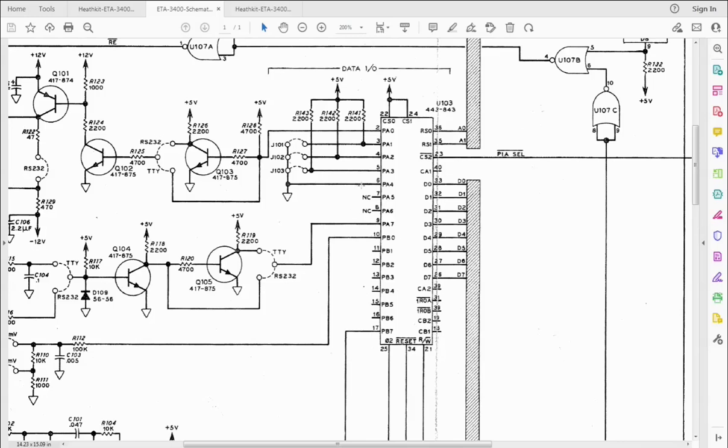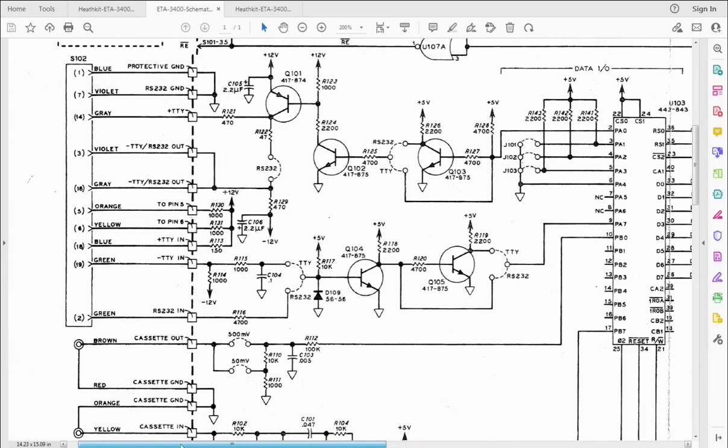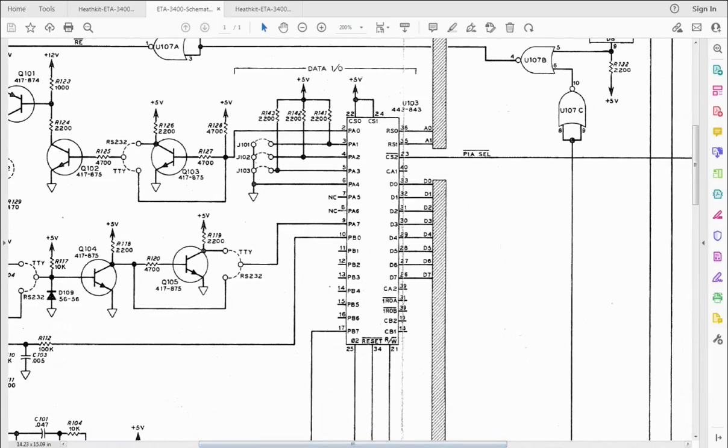The only other thing that this is used for is we also generate, let's see, yes, we also generate cassette signals in the same fashion using port bit 0 and port bit 7, and it uses a Kansas City interface, or standard, which was a standard used for writing to cassette in the early days.